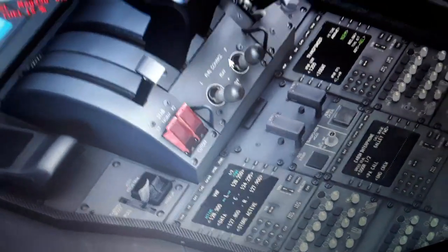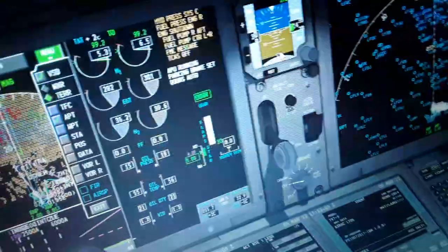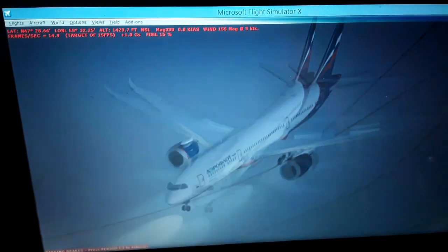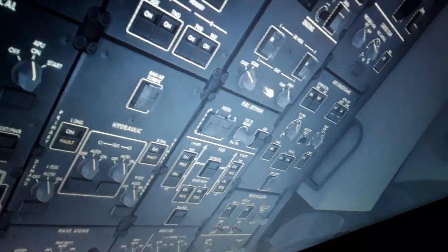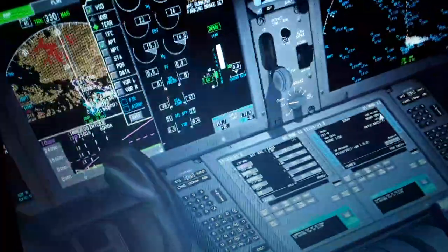So turn off both fuel controls to the off position. You will see what happens over here, fuel starvation. So we also have the amber indication. So we look outside. We have no fuel now to the engines, and the engines are shutting down. So we need to start the auto start system very quickly. Here you will see the amber reconfiguration switches, lights on.